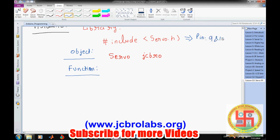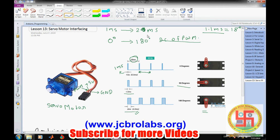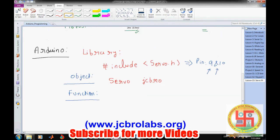So the servo motor should either be connected to pin number 9 or pin number 10 if you are using these built-in functions. You can also write your own programs very easily, because you just have to change the pulse duration. That can be done with the help of changing the delay time.